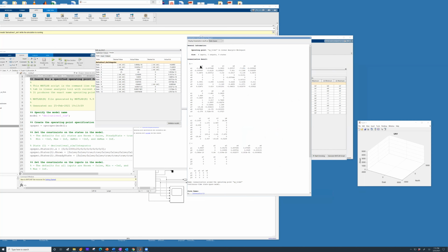That is the linearized model in state space. And please note, we have 4 inputs, 3 outputs. And what happened to the states? Initially, I had 12 states. Out of those, I have the linearization in 9 states. The linearization comprises fewer states, because after linearization, the derivative and the states become zero.